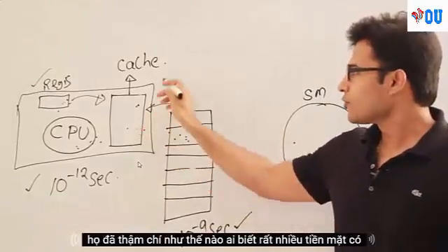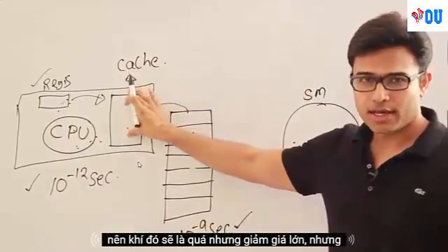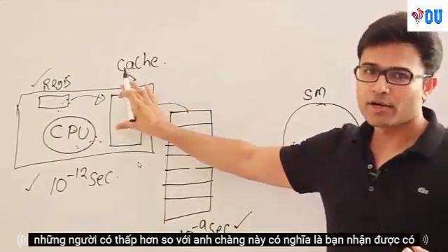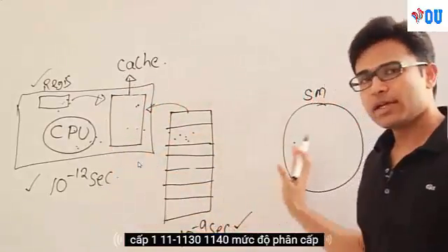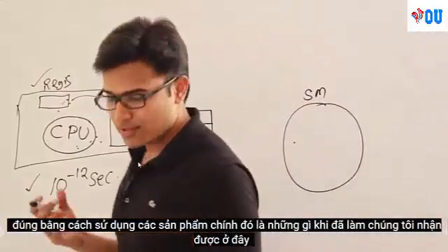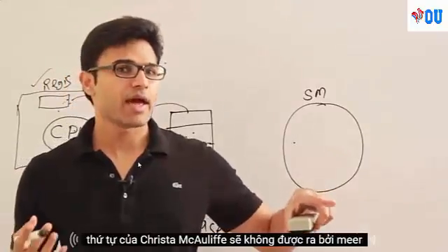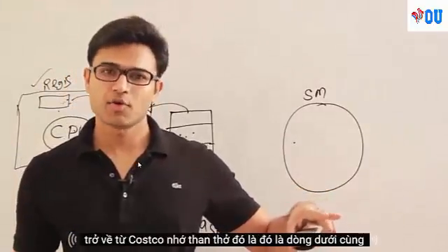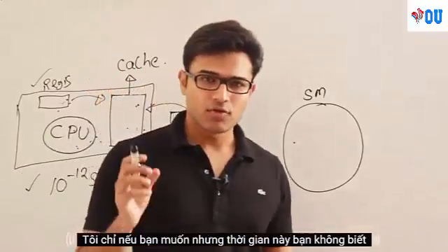Like this you can have any number of levels. Sometimes people even have one more level of cache, right? That cache will be cheaper compared to this cache, but it will be slower compared to this cache, which means you can have level 1, level 2, level 3, level 4, any levels of hierarchy, right? By using this hierarchy, the advantage we get is that the overall system cost will not be as high as the maximum cost memory element. It is actually normalized, right?